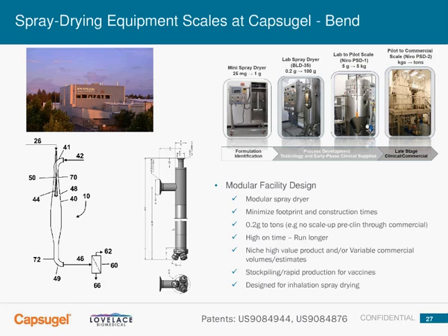Some other things that we're trying to look at: there are lots of different spray drying chambers out there in different sizes, and a lot of them are meant for multi-use. What I mean is that they can serve both inhalation or oral purposes with the correct atomizers or cyclones. But for inhalation purposes, we really don't need these large spray dry chambers. These very small droplets we have to produce to make these very small particles really don't need a massive 2 or 3 story spray dryer at the end of the day, like you might need for oral formulations or for the food industry.